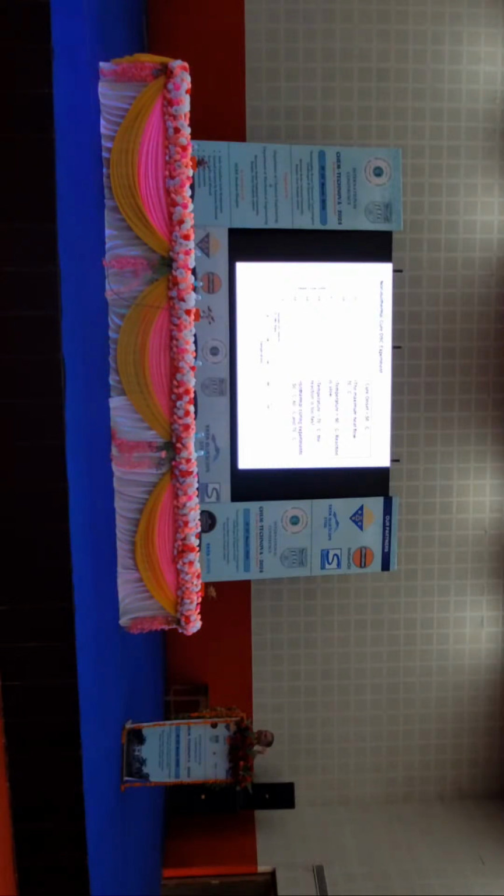As I told, we have done it for different resin systems. This is one of the vinyl ester epoxy resin systems. When I conducted the non-isothermal study, you can see that the cure onset is at 50 degrees centigrade, and the maximum heat flow is at 70 degrees centigrade. As I told earlier, I have selected 3 different temperatures between 50 and 70, which are 50, 60, and 70, for doing the isothermal studies.